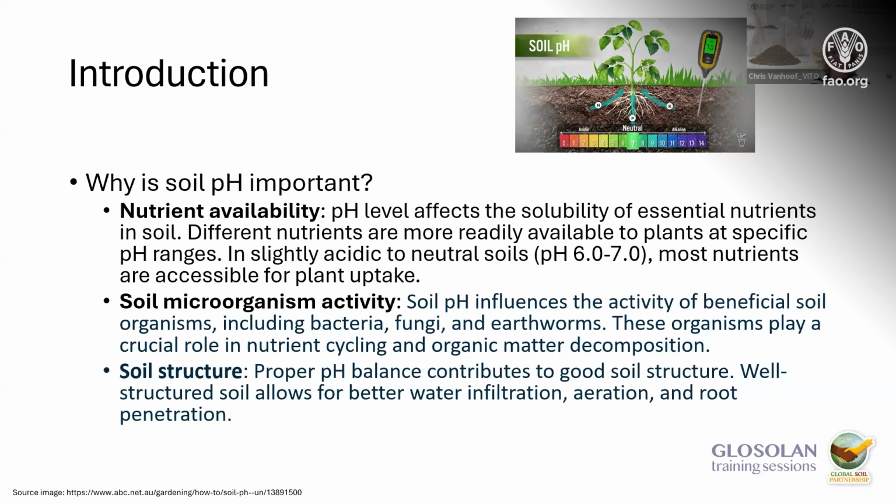And also the pH has an impact on the soil structure. You need a proper pH balance for a good soil structure because that allows a better water infiltration, a better aeration, and a better root penetration. So it's very important that the soil pH is at a neutral condition to perform a proper soil, a healthy soil.